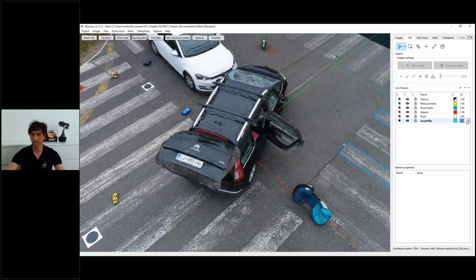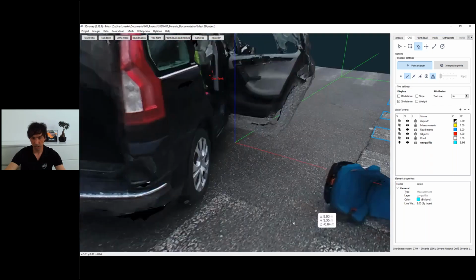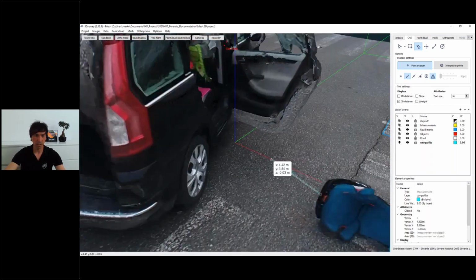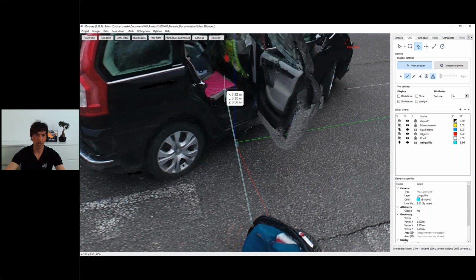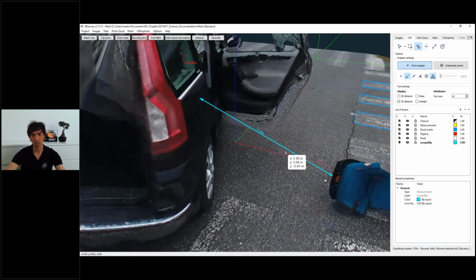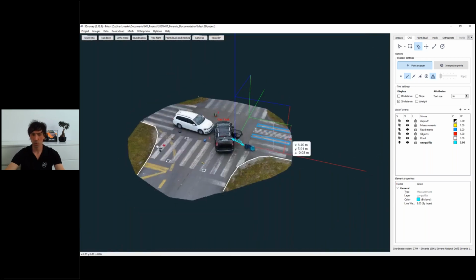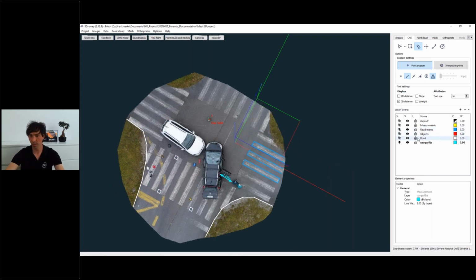made layer active, set the thickness of line, and for example, if I would like to measure here the 3D distance like I did in the presentation, I can actually easily snap here and up to here, let's say from the seat, and see this is a 3D distance 1.29 meters. Okay, so it's super accurately, and in this case we can get any informations out of it. Maybe just for your info, extracting those informations takes quite a bit experience.